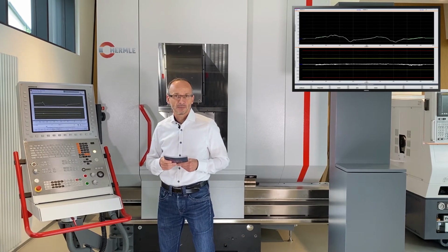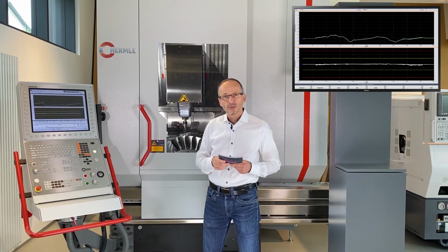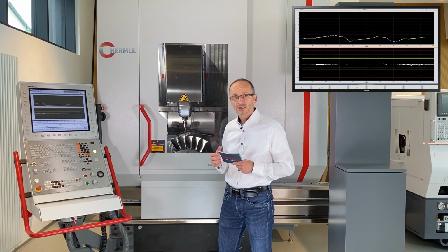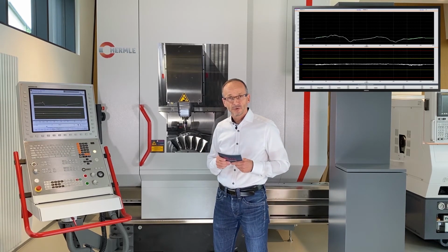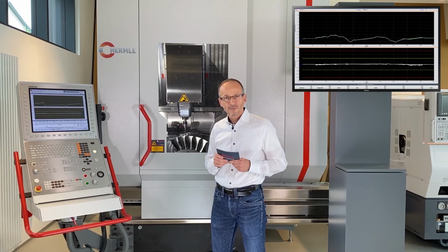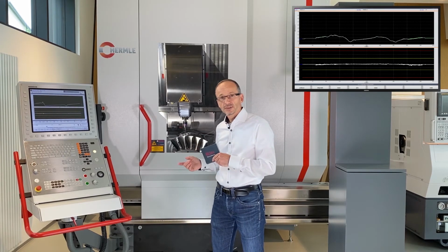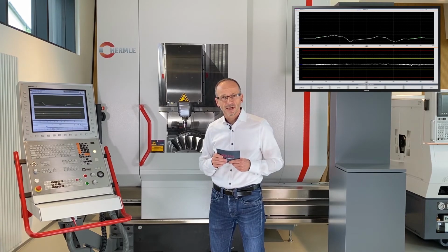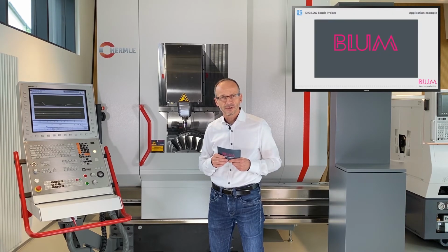And it's not only time we save when measuring; especially with this component, there's another particular advantage. Deviations between the target profile and the actual profile mean that the component can possibly be reworked. However, if the component is measured in the measuring room, it is no longer possible to rework it, as it is no longer in the original setup. When using a DIGILOG probe, monitoring is carried out directly at the machine while the component is still in the original setup, which means that the component can possibly be reworked.